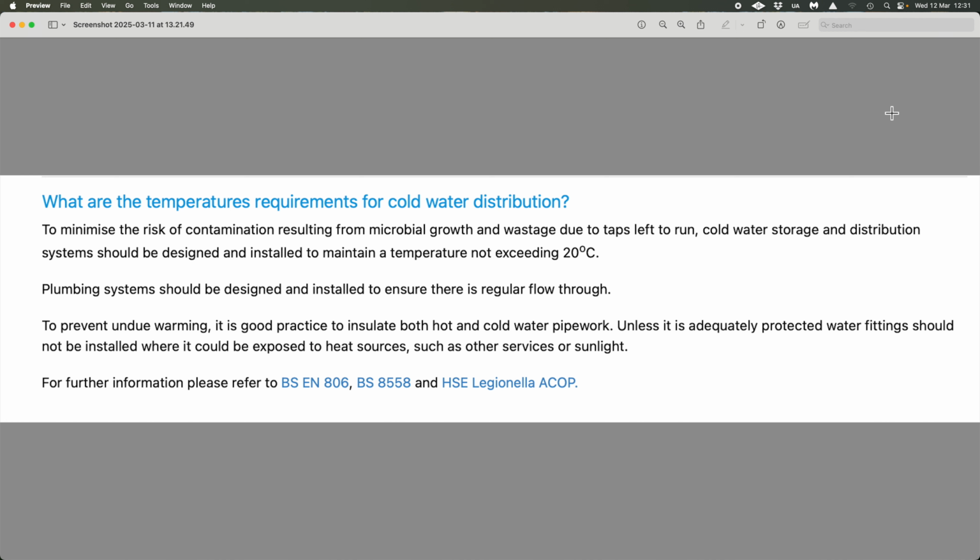So, water temperatures and flow rates of water. Water temperature, first of all, of cold water. If you're connecting your combination boiler up, you have the option of putting it onto the cold water mains, and let's be very, very clear on this: a combination boiler for the hot water side doesn't just have to be connected to water mains. It can be connected to a low pressure system, a tank fed system, or anything like that, so long as you can match the flow rates. We'll come on to that shortly. There are some virtues of doing it by stored water, and some virtues of doing it through mains, but we will come to that as we move forward.